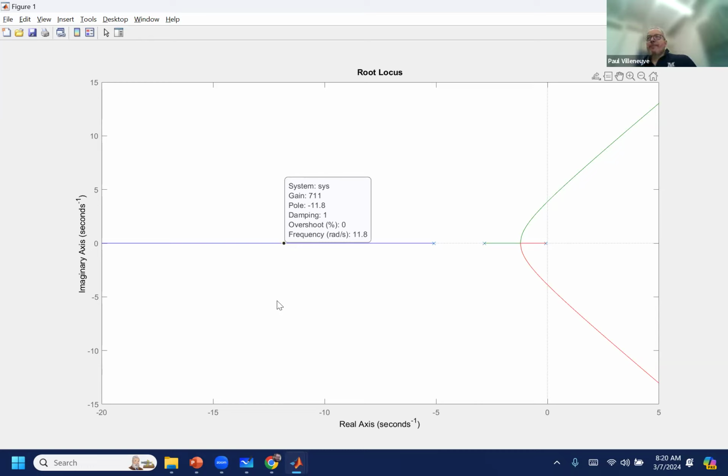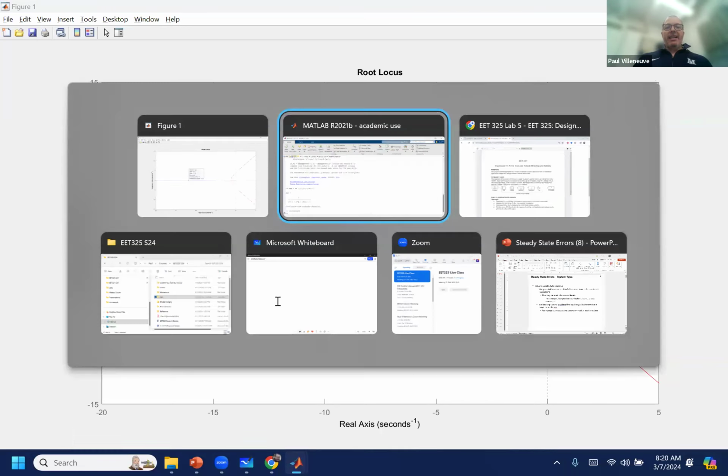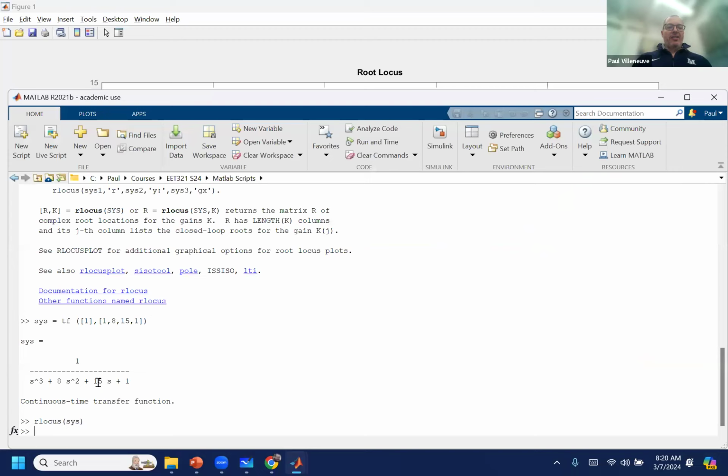Does this graph change if you change that value? Which value of one? Okay, the K, yeah, it's probably one for K. If you have a value of 1, K equals 1, then you don't do a root locus, you just have a single plot. But when you plotted this, in the transfer function, you substitute one. You can't do a root locus because when I do this transfer function in MATLAB, I can't have variables that are changing in here as well. So I can't have 2 variables. You can only have that one.